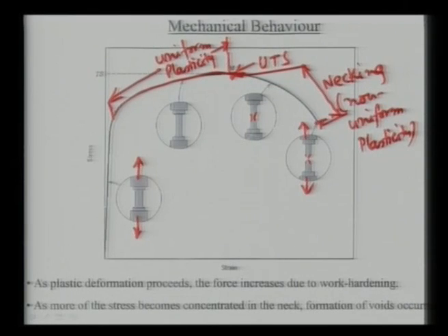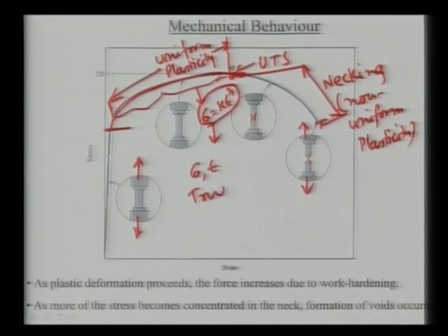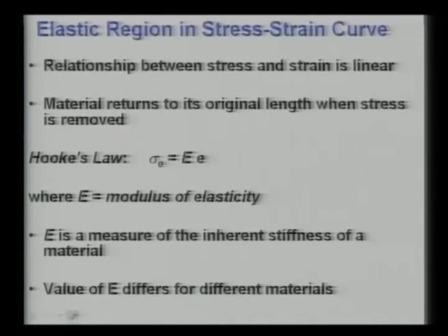Okay. Now you know how you can characterize the entire stress strain curve. You have the elastic part up to this point, then the non-linear plasticity behavior starts, and in this non-linear plasticity up to the point M, then your necking starts and the material goes to fracture. In this region of non-linear behavior one can roughly write that sigma is equal to K epsilon to the power n, where sigma and epsilon are the true stress and true strain values of the material. I will come back to this true stress true strain concept now.